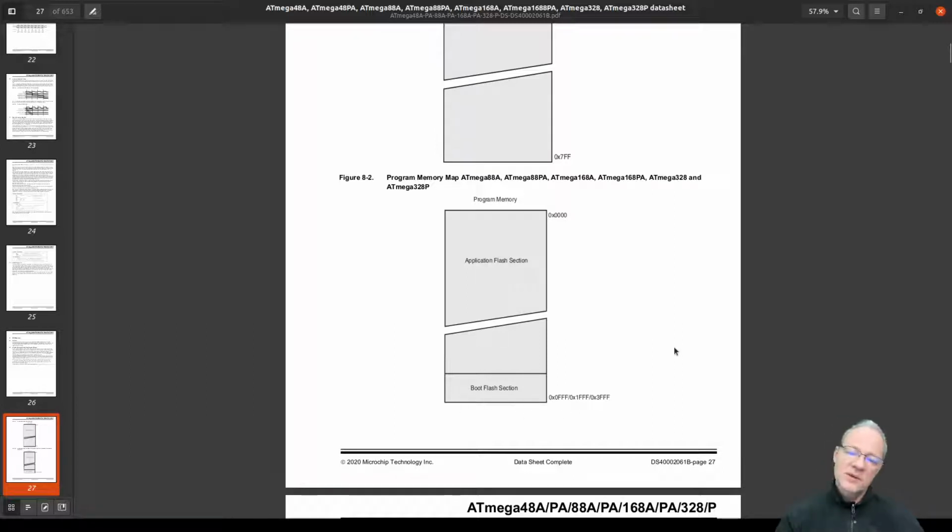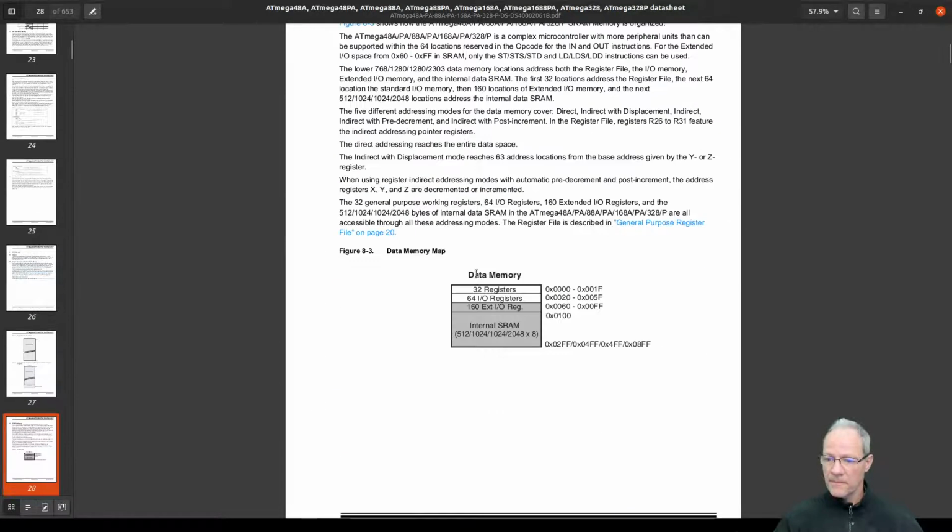So this is similar to a BIOS ROM on desktop computers. Basically you're going to have a small program sitting there that will be run every time you reset this system. And once you reset it, then you can decide whether you want to put this system into a programming mode or some other mode, or start a certain program from the application flash section.